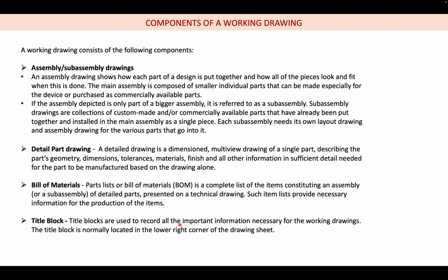So the title block gives the record all the important, necessary information for the working drawings. What is the scale followed, what are the units being followed, what is the angle of projection which is followed, who prepared the drawing, who verified it, all those details, and even some other details. So these all constitute a working drawing.